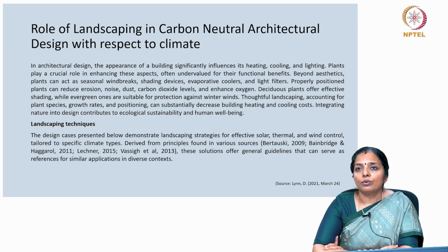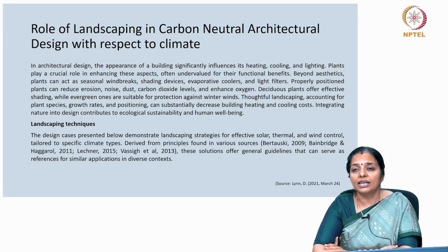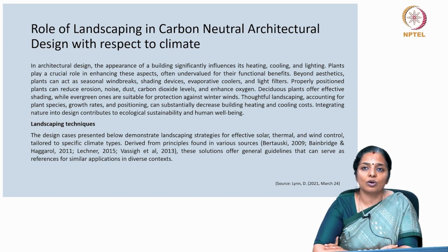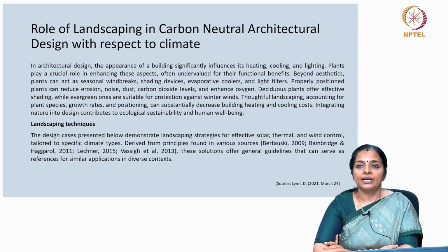Plants can also act as seasonal windbreaks, shading devices, evaporative coolers and light filters. Properly positioned plants can reduce erosion, noise, dust, carbon dioxide levels and enhance oxygen. Deciduous plants offer effective shading, while evergreen ones are suitable for protection against the winter winds.